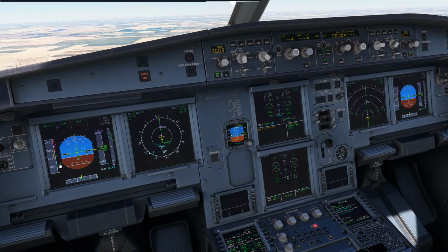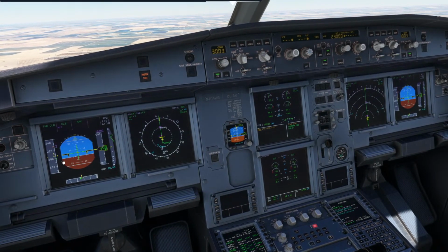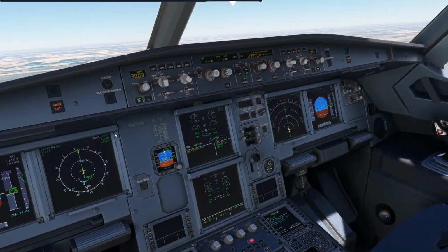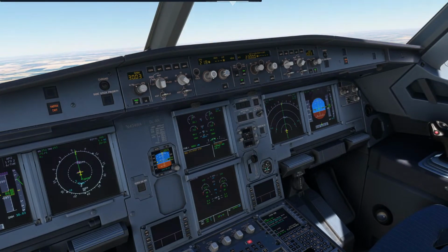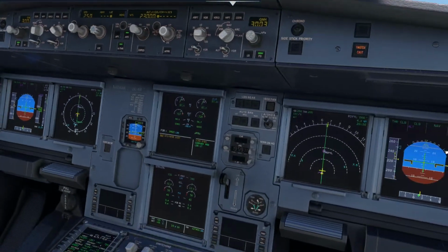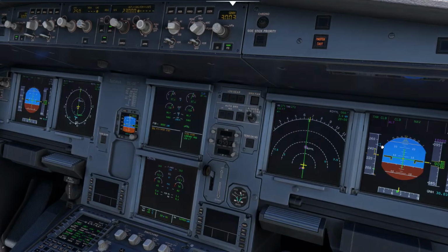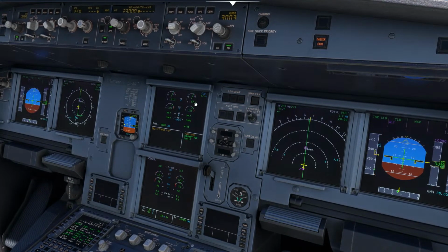When you're above S speed, you can retract flaps. You know what green dot is? That's like your best glide. That green dot on the airspeed indicator is like best glide. So I'm going to go to 250, and I'm going to go to set speed, so it'll just level change, flight level change, 250. And I'm going to pull out. If you notice, the airplane is now going to pitch for 250 knots at climb thrust.